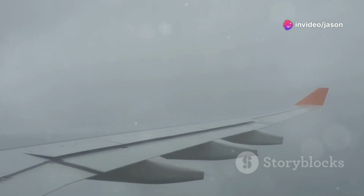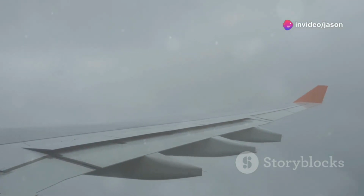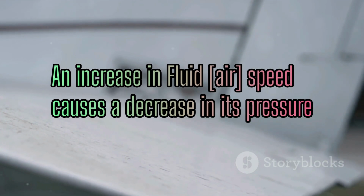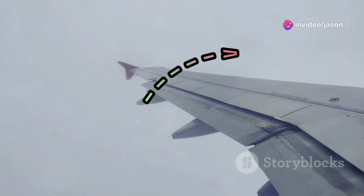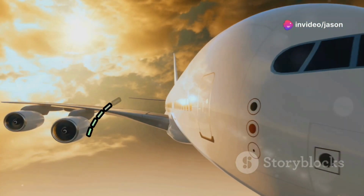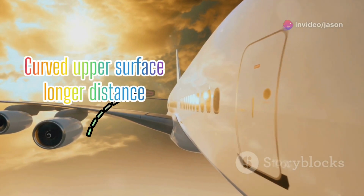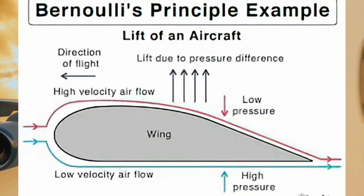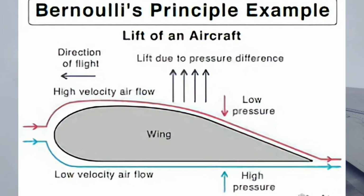Now let's talk about a principle that's key to understanding lift, Bernoulli's principle, named after the Swiss mathematician Daniel Bernoulli. This principle states that as the speed of a fluid, like air, increases, its pressure decreases. But how does this relate to flight? Imagine air flowing over an airplane's wing. This wing's curved upper surface forces the air to travel a longer distance than the air flowing under the flat bottom surface. This difference in distance means the air on top has to move faster.